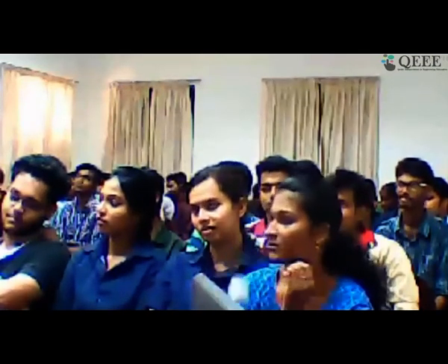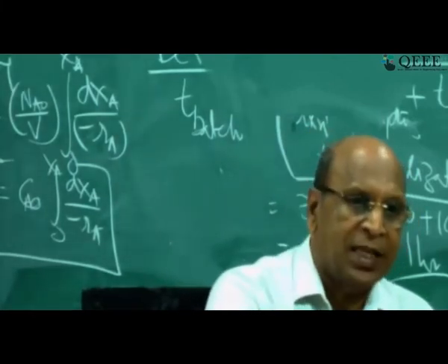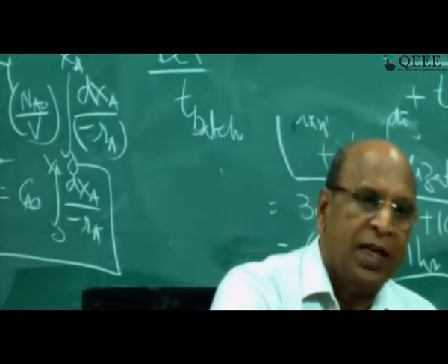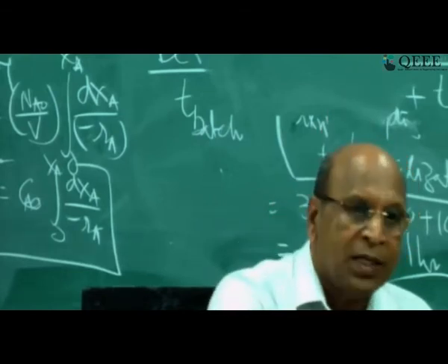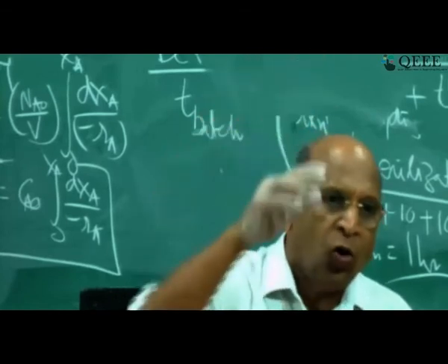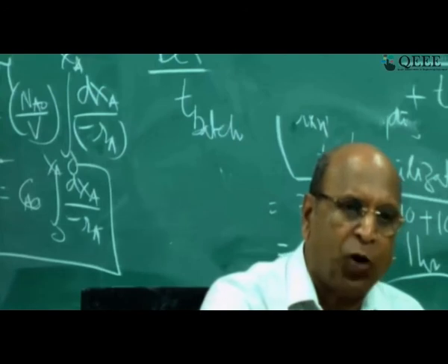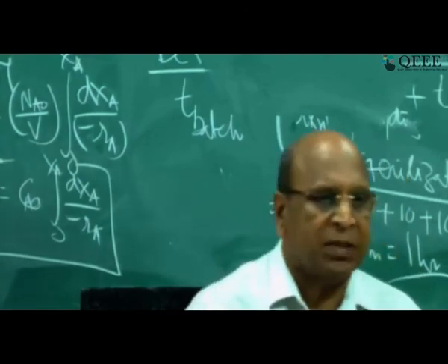Yeah, see, plug flow is when you have that kind of high velocities and the reaction is very fast at any cross section. Also please don't imagine that the diameter of the tube is 1 meter. No, the maximum diameter that is used, as far as I know, for plug flow is maximum 8 inches.